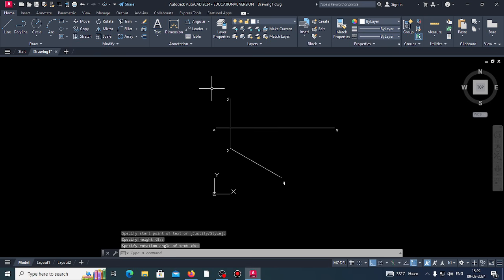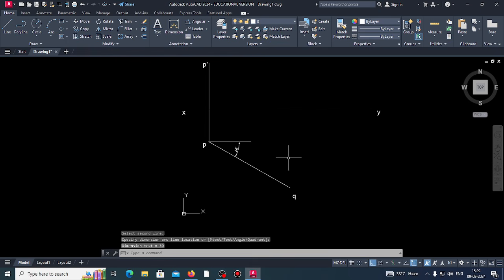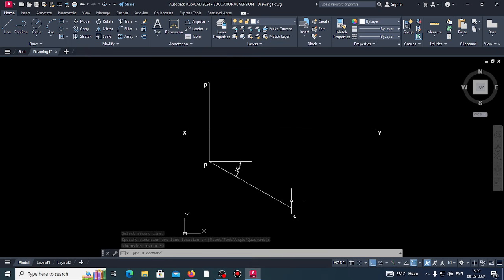Okay. Now you can draw a single line, the reference line, locus of P, and you can give the angular dimension there and then for reference. Now in the front view, this Q point, the other end, will be on this locus of P, and the intersection will be Q dash.